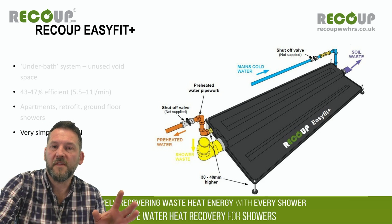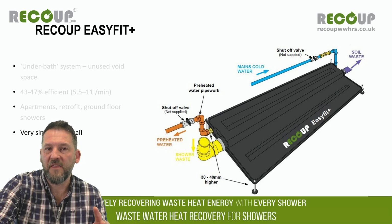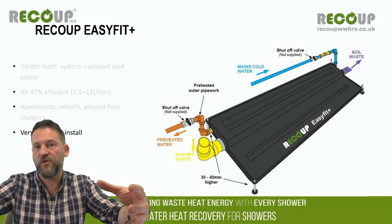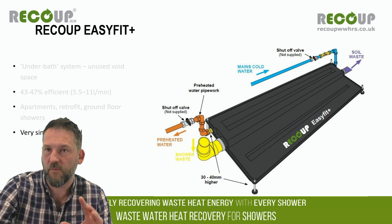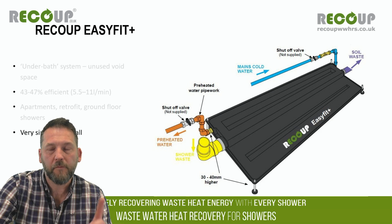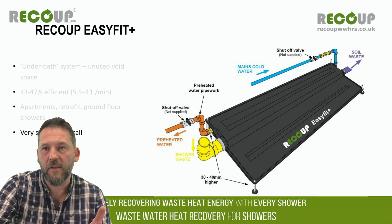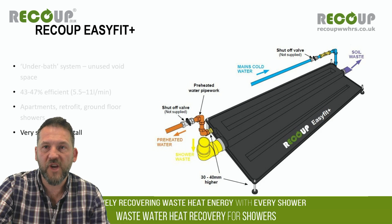The Easy Fit works in the same basic way as the pipe system does. Warm waste goes in one side. In this case, it floods out across the base of the tray, and then that will vent off to the SVP as per normal. So again, we're only interested in the energy, not the grey water. Cold water main comes in the opposite side, so for counterflow heat exchange. In this case, we've got a flat serpentine heat exchanger, so lots of surface, rolls all the way through in the serpentine way, comes out preheated. Again, double check valve, 2 isolator valves, that's all that's required for installation.